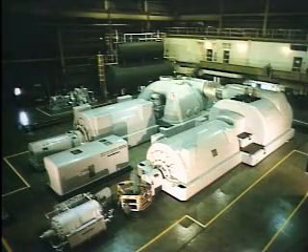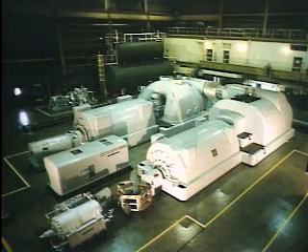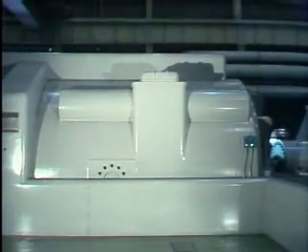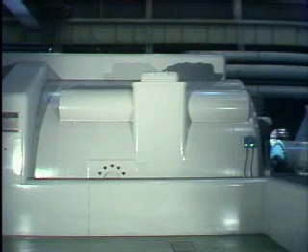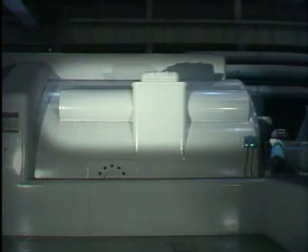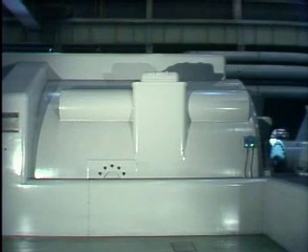When a generator is cooled with hydrogen, the hydrogen gas is pressurized and sealed inside the generator so that it doesn't mix with air. This means that the heat has to be removed by a cooling system. This generator has 4 hydrogen coolers, located on the sides near the top. Each hydrogen cooler is basically a shell-and-tube heat exchanger. Cooling water flows through the tubes inside each cooler and absorbs heat from the hydrogen.